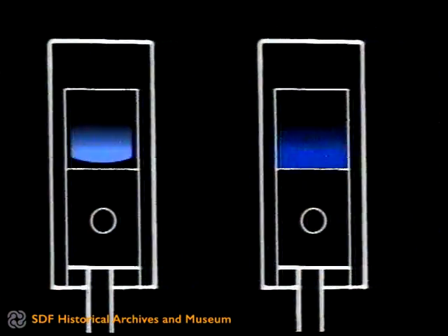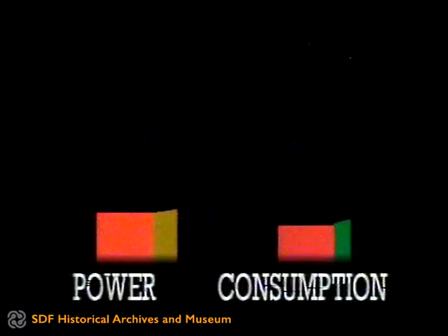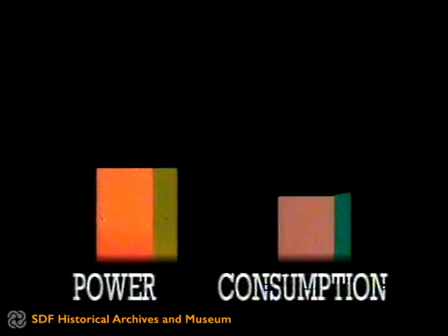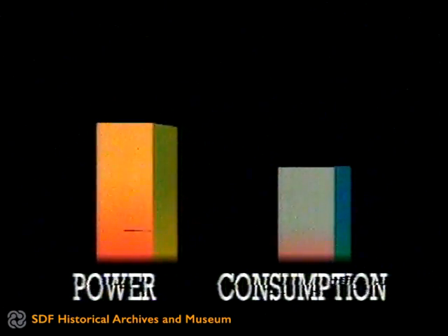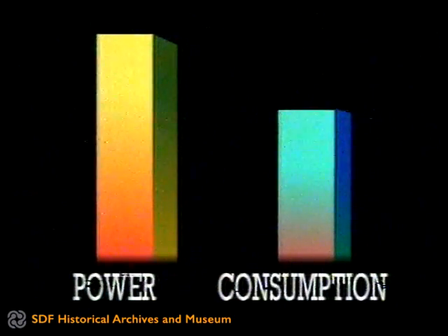Why does the specific consumption improve? Turbocharging increases the volumetric or induction efficiency of the engine. That is, it improves the filling of the cylinders, with the benefit of the power that can be generated from the fuel burnt. Power increases more than fuel consumption, thus giving rise to lower specific consumption figures.